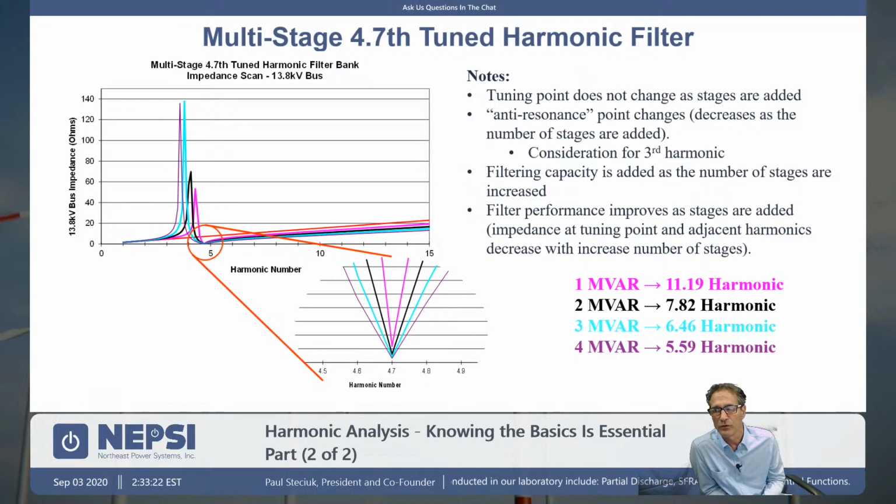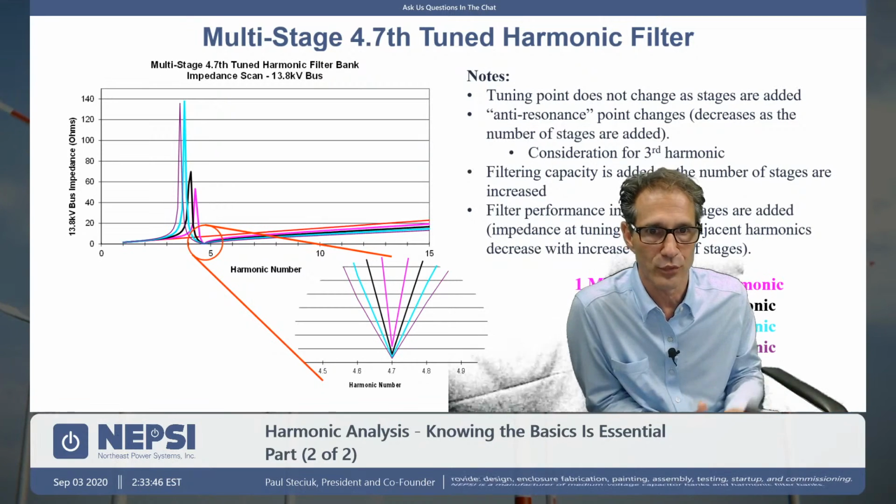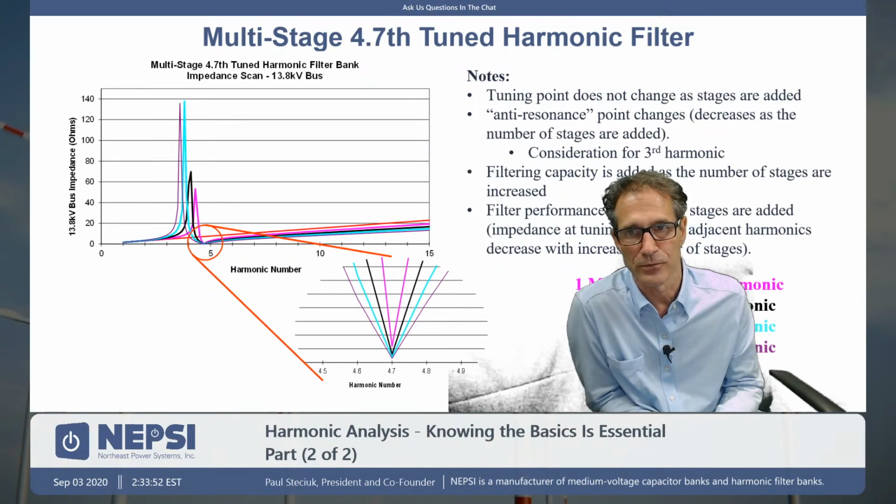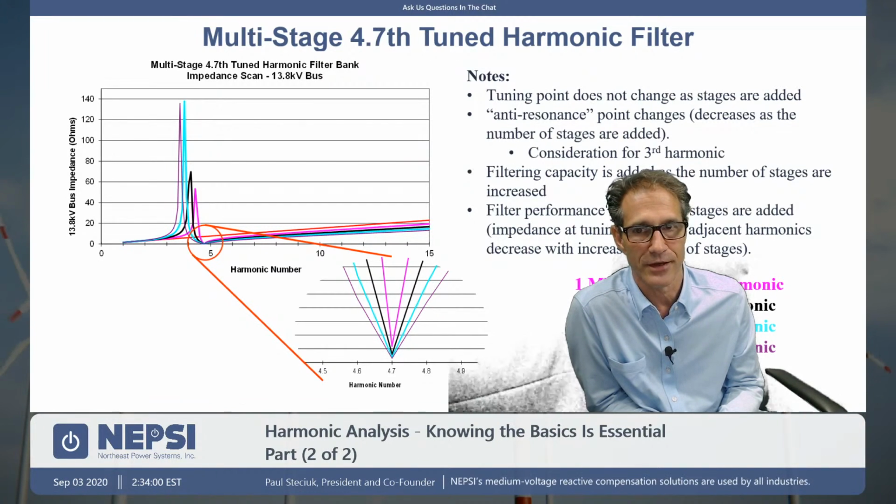Well, in the low voltage industry, which I was involved with 25 or 30 years ago, the industry basically standardizes. They will standardize on this detuned concept, 4.08, 6% reactor kind of a thing, or they will go with 4.8. But almost always, it's a 50 kVAR step, 100 kVAR step. This is what we have seen in the past, 50 kVAR steps and 100 kVAR steps. It's more of a mass assembly, off-the-shelf design concept.